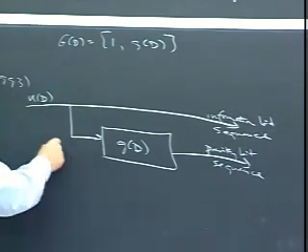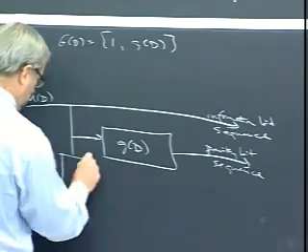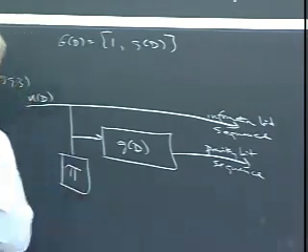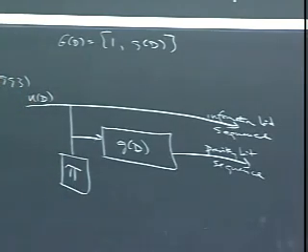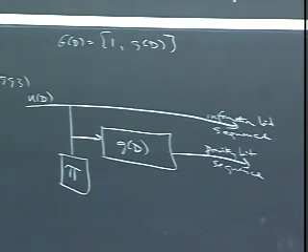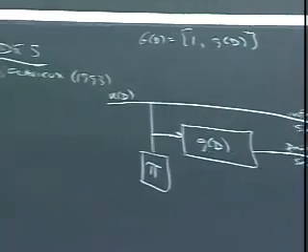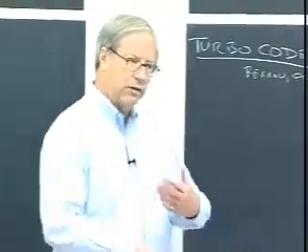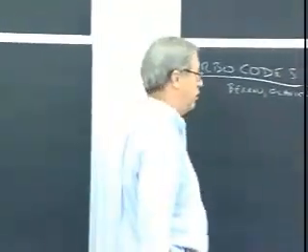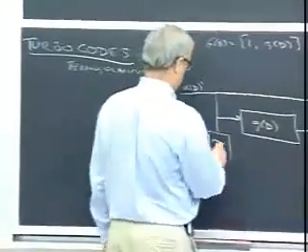Now, let me take the same information bit sequence and put it through a large permutation, which again I'll represent by pi. I want you to think of this as taking a 1,000-bit block and mixing it all up or something like that. Actually it's better to use a so-called convolutional permutation, which is kind of stream-based, continuous, the same way the convolutional codes are.